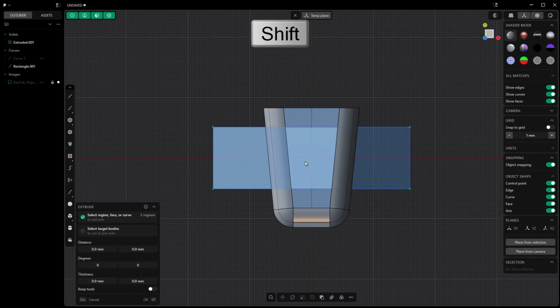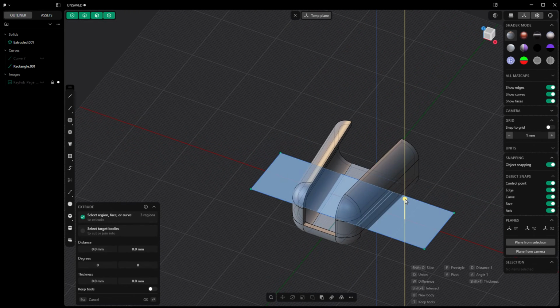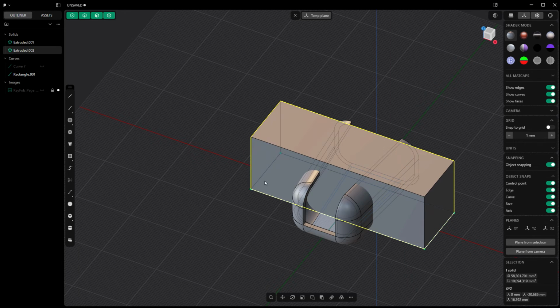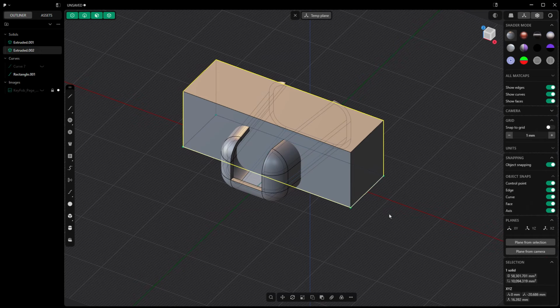Now I'm going to select each of these regions. Because we use a construction plane based on a face, it automatically brought in its profile. But we want to select those 3 regions and pull them up until they're all the way through our solid object and right click to confirm. Now the reason we did this as opposed to just removing it automatically is because I don't want this extrude to start from that plane.